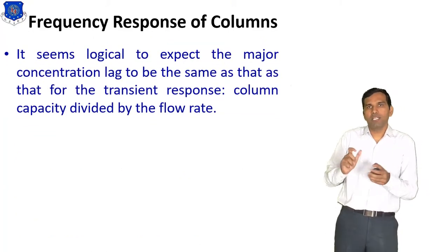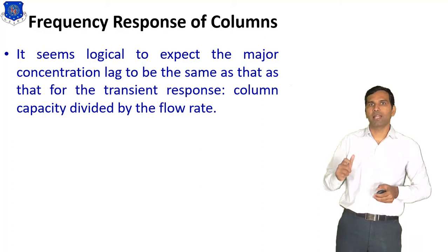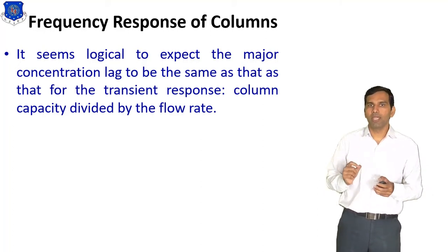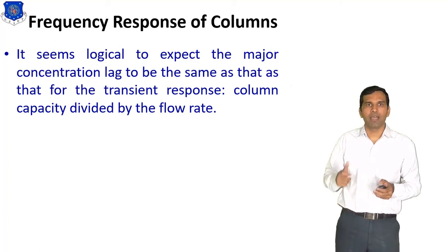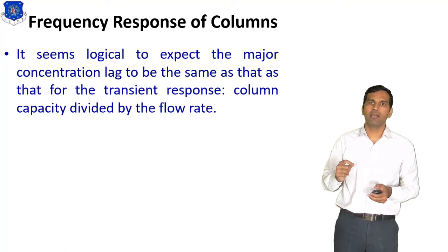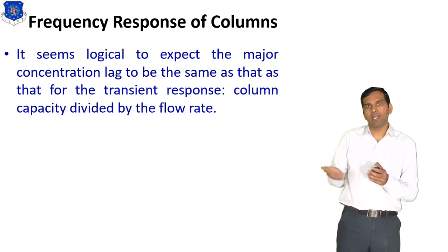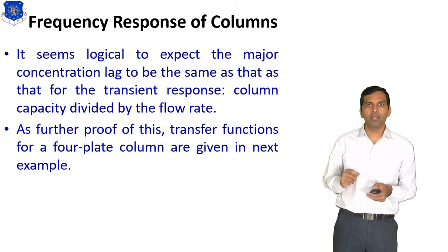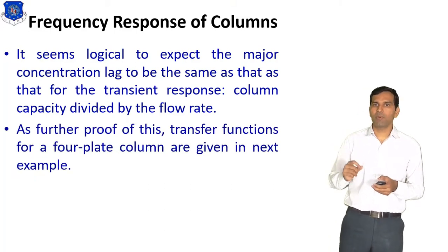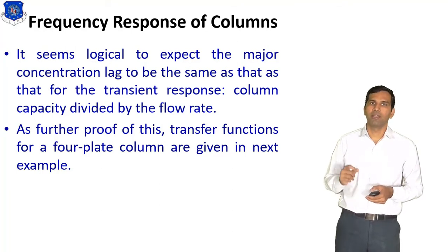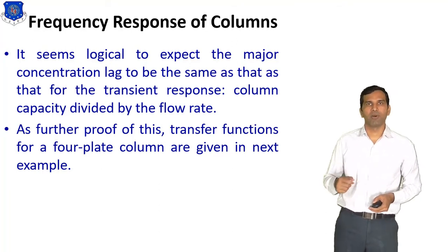It seems logical to expect the major concentration lag to be the same as that for the transient response, like column capacity divided by the flow rate. The transfer function for the 4-plate column is given in my next example.